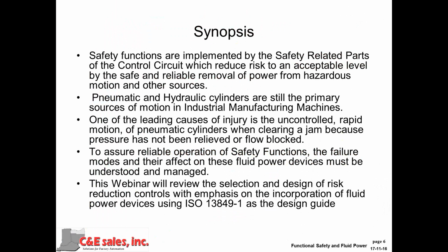Hydraulic and pneumatic cylinders are still one of the primary sources of motion in the industry, and one of the leading causes of injuries is the uncontrolled rapid motion, especially of pneumatic cylinders, when clearing jams because the pressure has not been correctly relieved and/or the flow blocked.